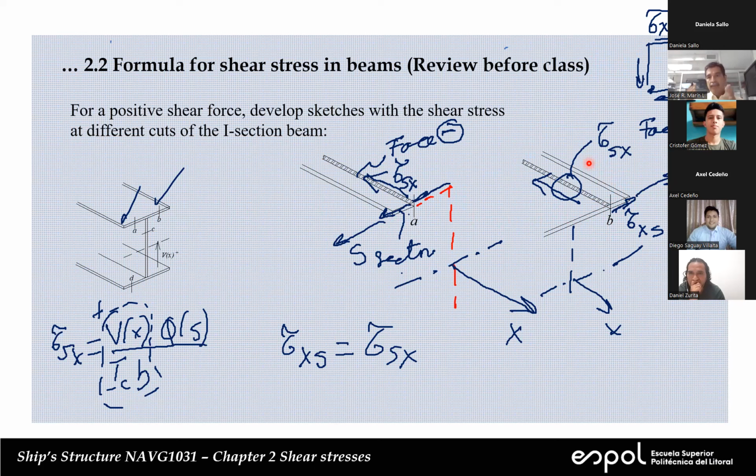We calculate it with the formula that we have deduced. We have only one formula. We can calculate the tau at the cut, and we integrate from there all the way, defining this sector. The sector ends at the point where we know the value of the stress. The value of the stress at the edge is 0. We know that value, so we have one equation, and we can apply it to get one unknown.